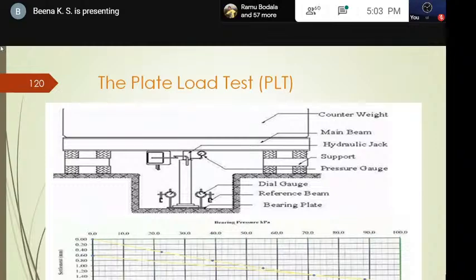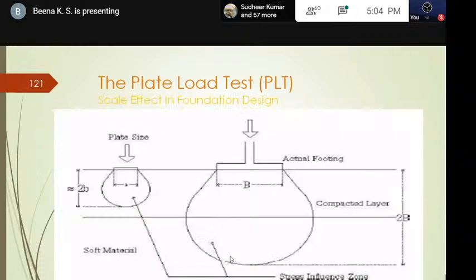In normal cases of a general shear failure, as we said, it's a sudden failure. There we reach a level at which we won't be able to maintain the load on the jack. At that time, we can see that the settlement dial gauges will be running fast, and you can get the shape of the load settlement curve in the downward direction.